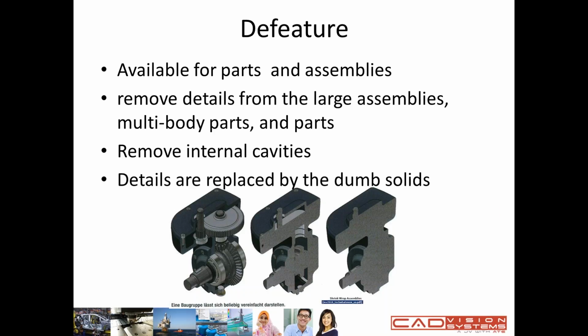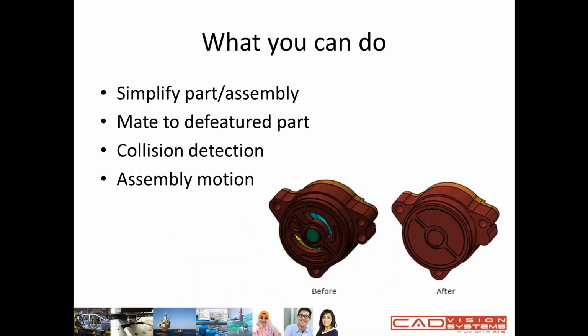Okay, go to the next one. So what can you do with the defeature tool? You can simplify the parts or components like the picture below, before and after. Before you apply the defeature tool, you get all the details, and once you apply it, it will cover all the cavities and also take out the detailing of your component.